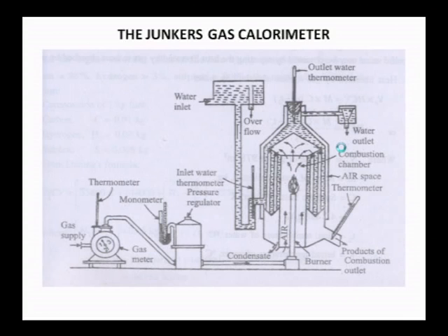So, water absorbs the heat. As a result of absorbing the heat, the temperature of the water increases. That temperature you have to record with the help of the outlet water thermometer. Now, the products of combustion will find their way to exhaust to the atmosphere. They need to be cooled.